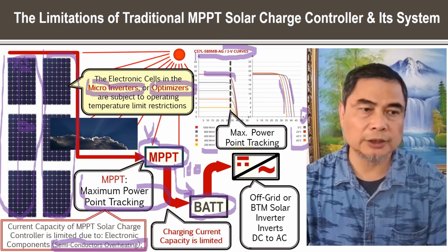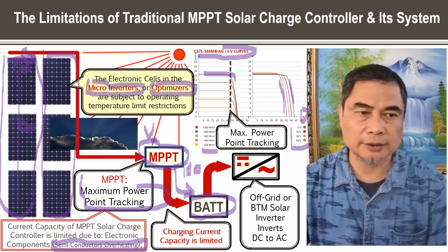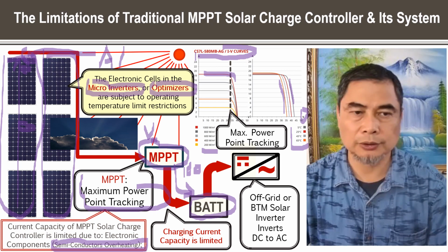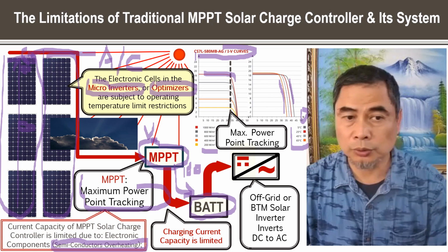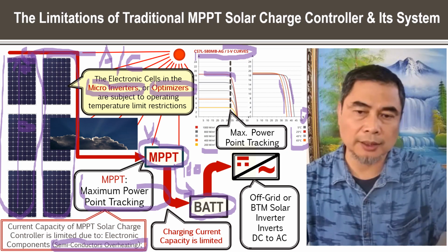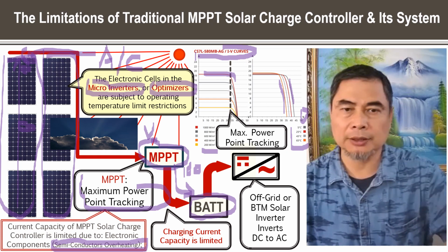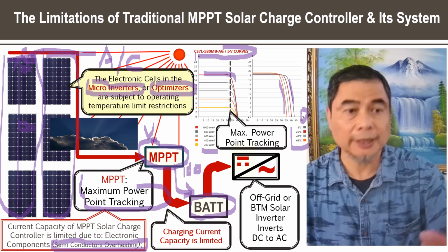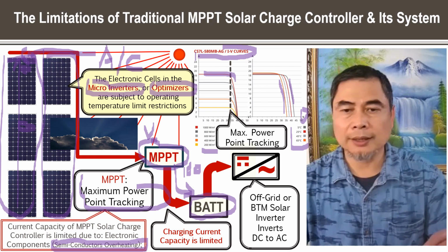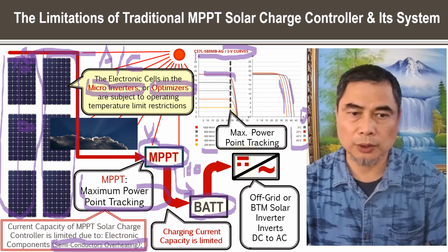A micro inverter is built behind each and every panel. These are small electronic devices that change DC to AC directly to power the AC load. And as you can see, this micro inverter is also working in outdoor weather conditions. It could be minus 40 degrees, could be positive 65 degrees Celsius, and their behavior changes. So this is another reason it ends up with a high maintenance cost for those kinds of systems as well.